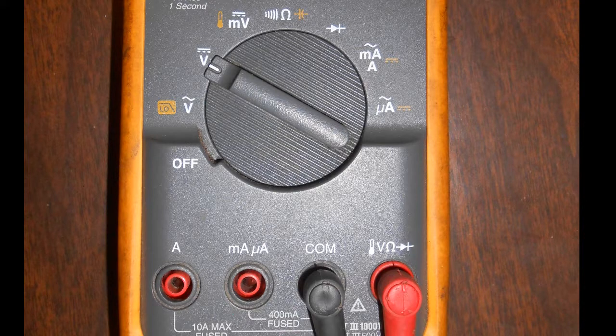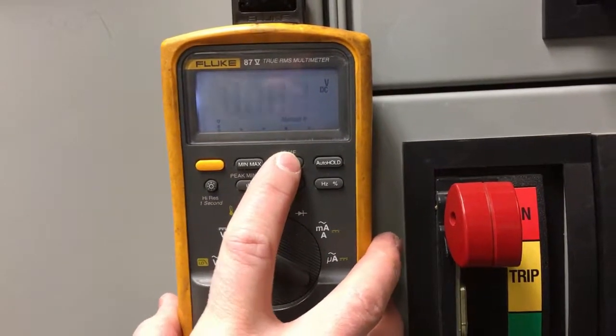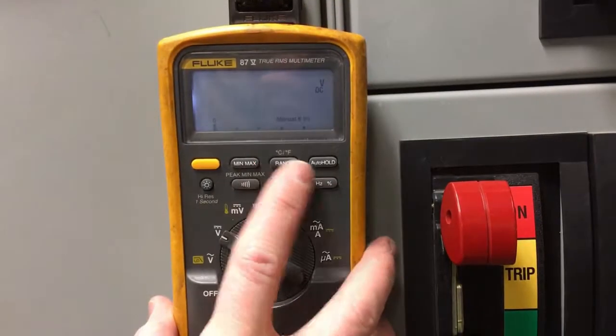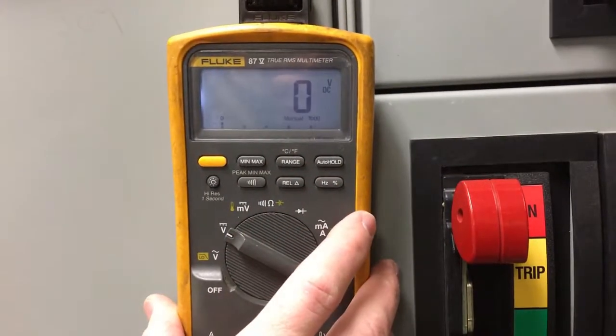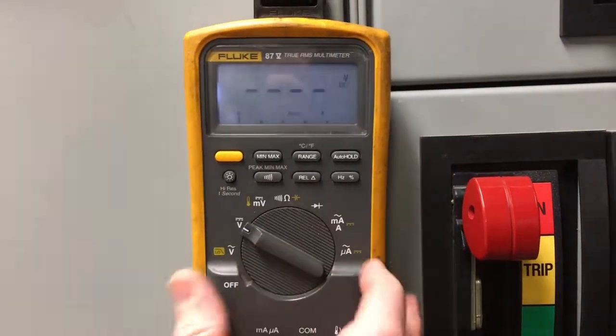The next selection on the dial is DC voltage measurement. The lead connection for this setting is identical to the AC voltage measurement. Just like the AC voltage, most meters will default to an auto range mode, with the option to select a manual range. In this mode, the unit of measure will be in volts only and will not have a millivolt unit, which is instead provided at a separate dial selection.